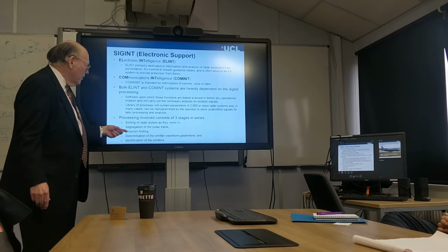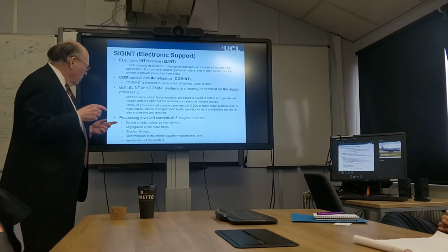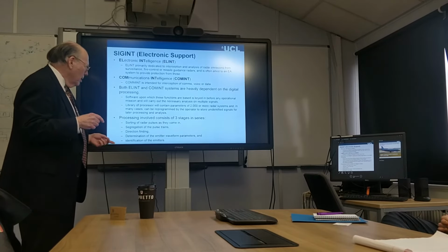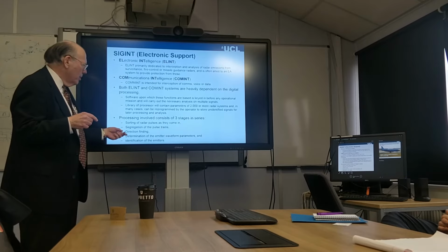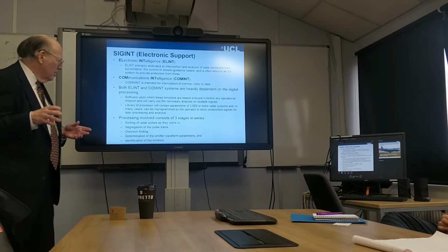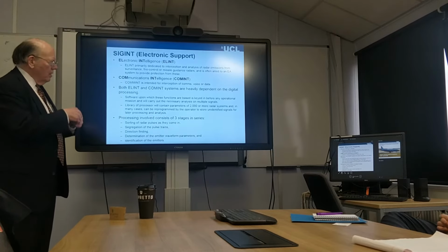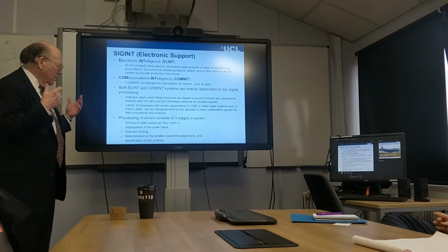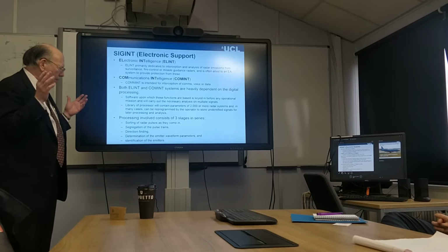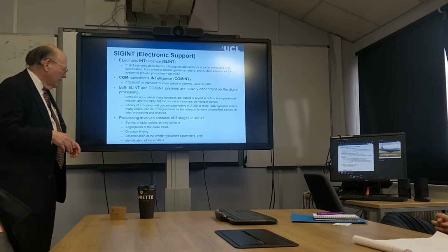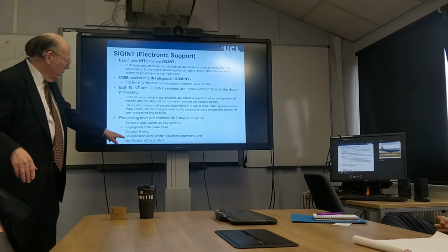We do the direction finding to locate it. And we do discrimination of the emitter waveform parameters and identification of the emitter. So waveform parameters could be pulse width, pulse repetition frequency, any modulation on the pulse, etc. And ultimately, we want to identify the emitter.